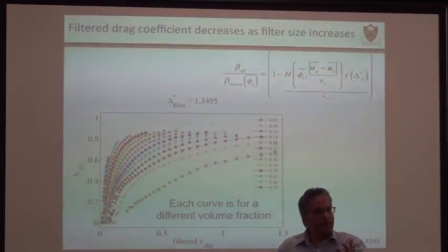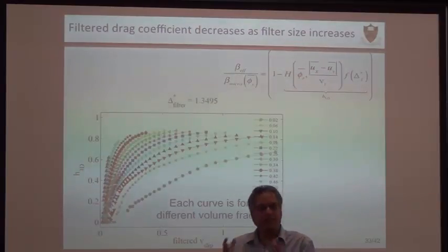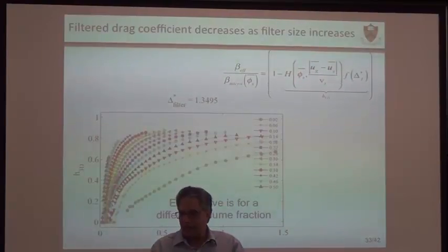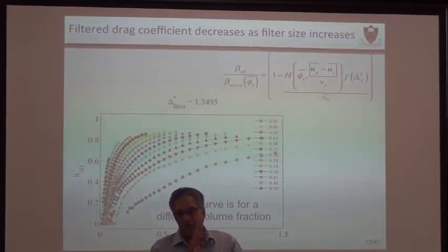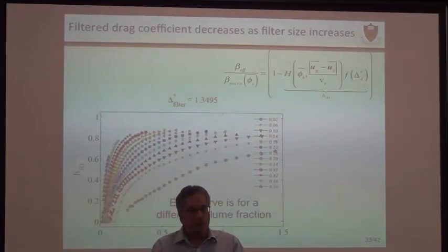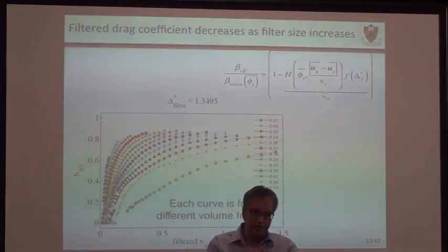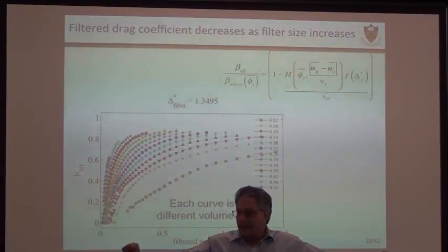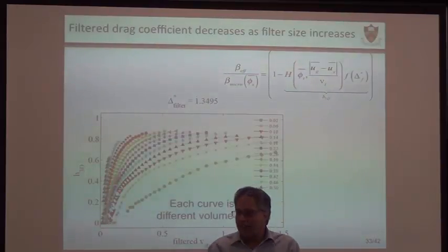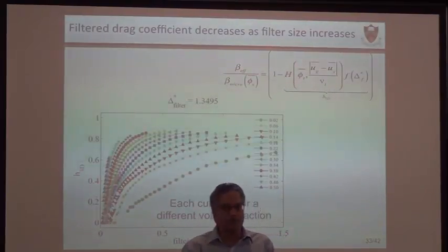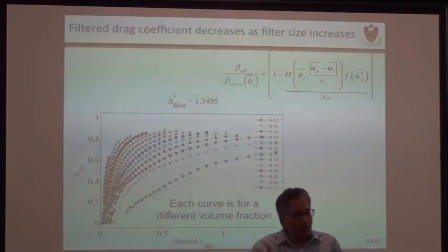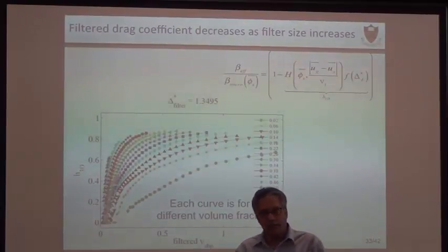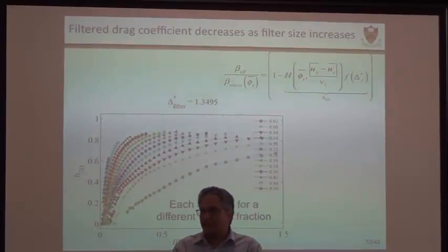The reason why it happens is because this one lumps many things into it. It lumps the tendency of the particles to segregate and the drag force it produces all into one. When you have a higher relative motion between the gas and the particle, the gas pushes the particle more vigorously away, creating a bigger path, and that in turn creates less communication between the gas and the particle. The gas goes faster. That's why. It is because the gas flow rate relative to the particle influences the microstructure in a way that the higher the slip velocity, the higher the segregation, and therefore the lower the drag.